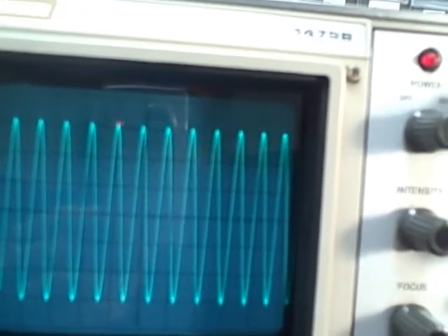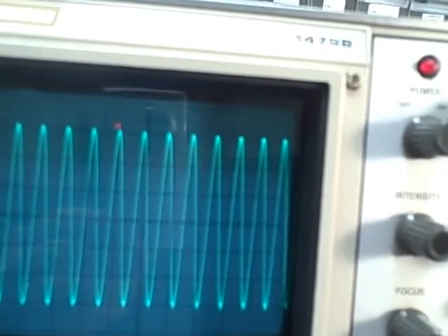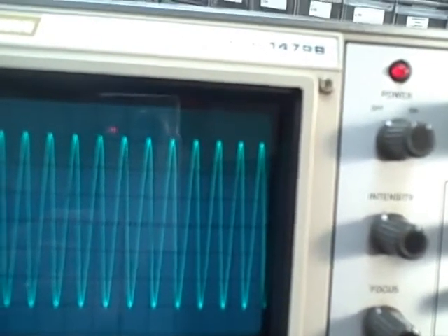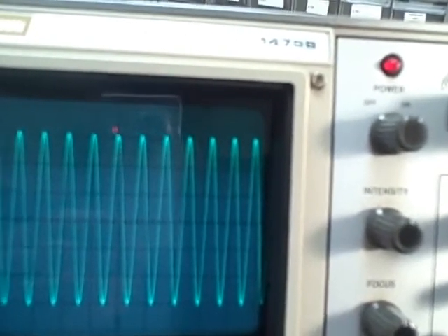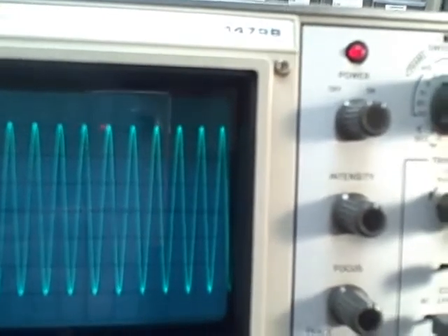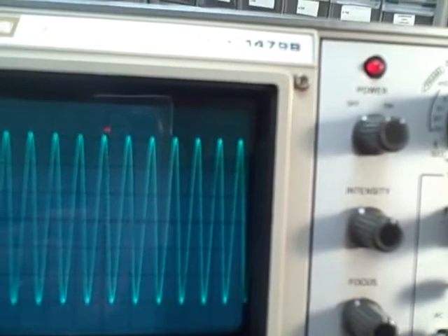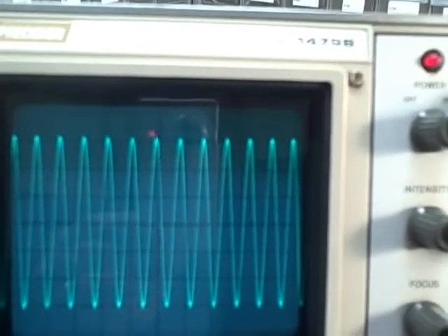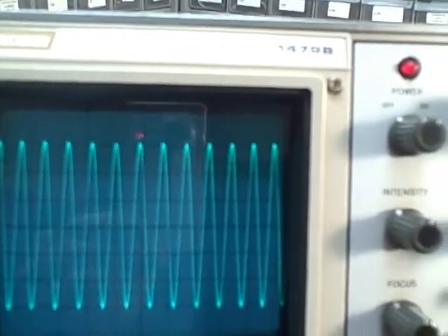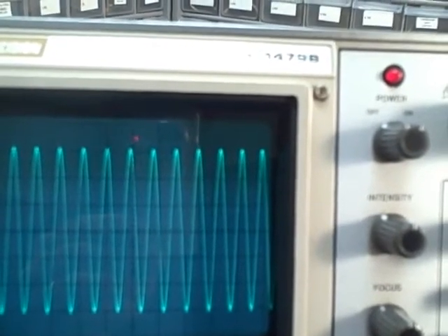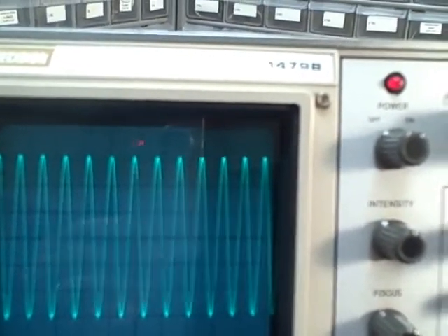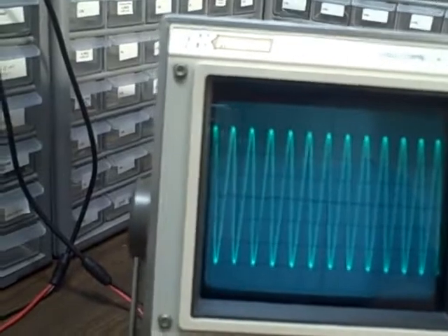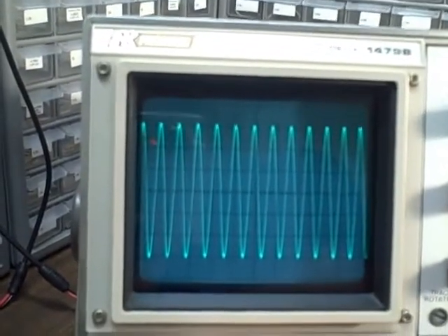And the magic number for anything that's plus and minus 4 divisions would be plus and minus 2.8 divisions, which would be the 3 dB down point. And we haven't hit that. We're close. We're at 3, but we still could come down another 0.2 of a division. So the point is, we are slightly better than the spec that the scope bears. So we have not hit the 3 dB down at 30 megahertz. We are just slightly better. That's on channel A. And if I move to channel B, we should be able to see the same results.